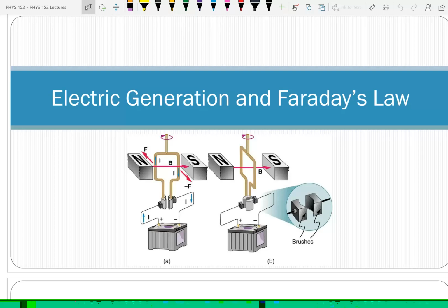What is this solenoid made out of? Wire is what I was looking for. Just simple. It's wire. What's the resistance of that wire? I know you can't give me a number, but you can give me a range. Small resistance. If I put 120 volts across a small resistor, what's the current going to be? Really big. Well, if it's more than 15 amps, I'm going to blow a fuse or something. So I have to do this quickly. If I just plug it in and leave it in, it's going to blow a fuse, well, circuit breaker. So I always have to do this kind of quickly.